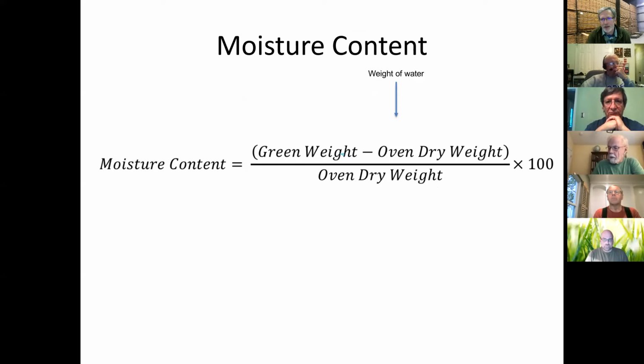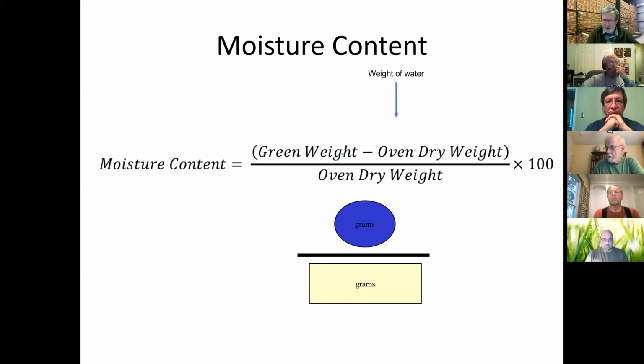There's actually an ASTM standard for this. So it's a very standardized, normal way of determining moisture content, okay? So it's the ratio of the weight of water to the weight of oven dried wood. It is a ratio. Can I have over 100% moisture content? Yes, I can. So think about balsa wood. If you have a volume of balsa wood, what is in most of that volume? Air. So imagine if you put water in all that void space, what would weigh more?